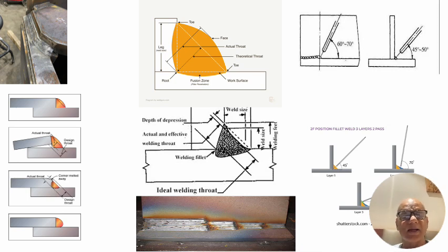And that's where I decided to make these 3 separate slides on the fillet, irrespective of the material. If the material is sluggish, and if the material is not going to flow, and if there are nozzles where the accessibility is an issue, then our welding is going to become a further challenge. And that's where, don't take fillet welds very easy. They are also equally important for us. And a small defect or improper welding can create a failure. As we will see in the next slide, the stress concentrations are going to be much higher.